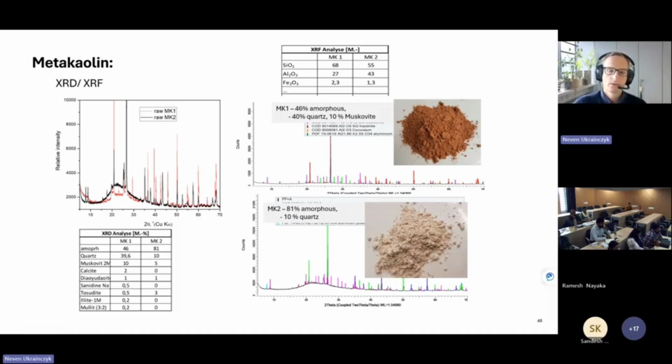If you burn too much, the calcination, the optimal calcination temperature and duration, is important. If you burn too much, you will start to get mullite peaks, and you don't want that because mullite is not reactive. So you should not see mullite peaks on your XRD. And here we characterize two different ones. This is the mixed clay with illite, and this is a pure metakaolinite.